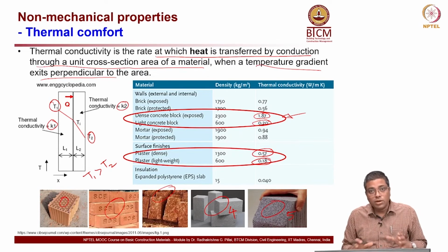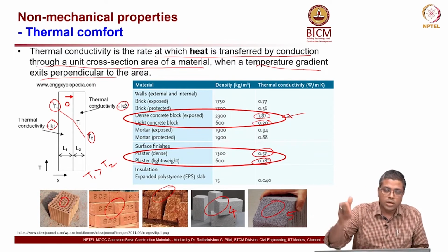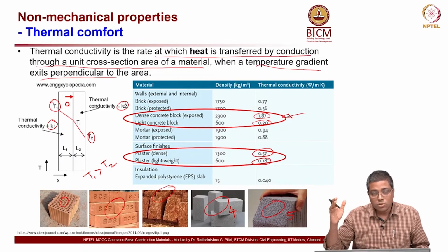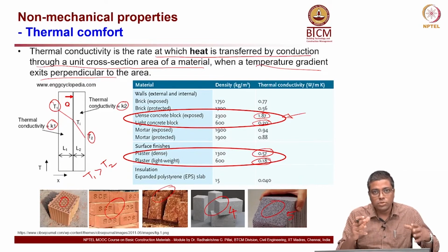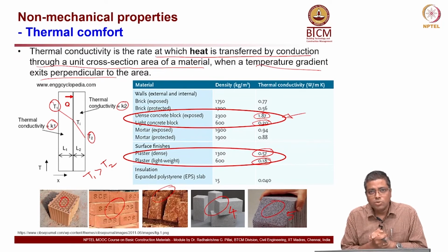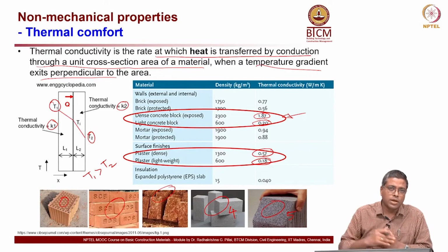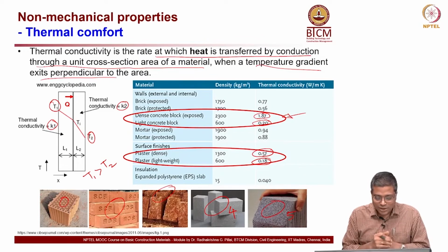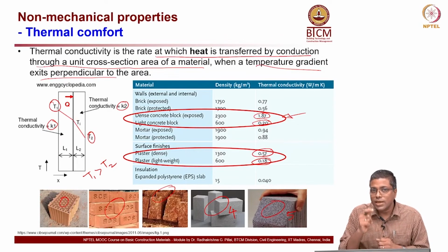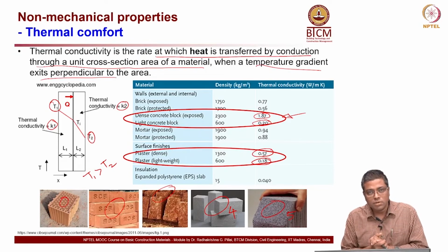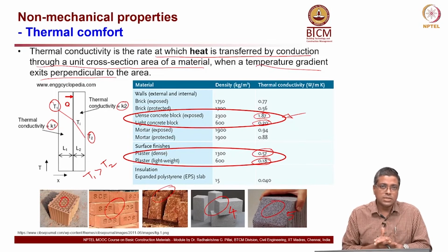For example, in buildings where you have a wall, if you are talking here, people in the other room need not listen to what you speak. In today's construction, where they use very high quality concrete, you will see that this is becoming a problem: somebody speaking in one room, the people in the other room can actually hear. So, you should think about what type of material to use for interior walls in buildings. We should use brickwork, or whatever material we use should have good resistance against noise. They should function like a noise barrier.